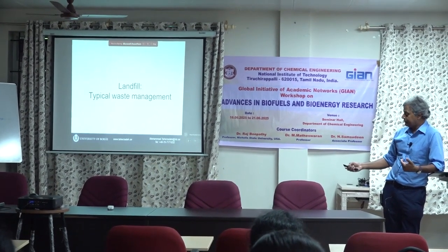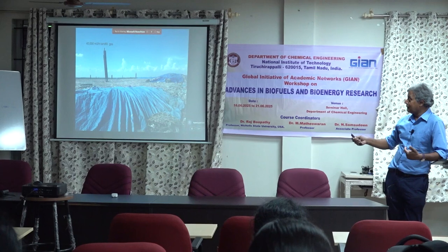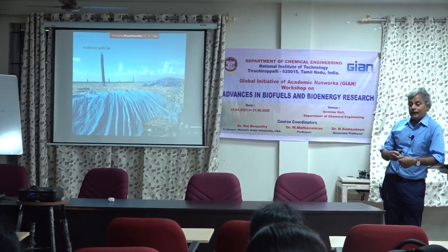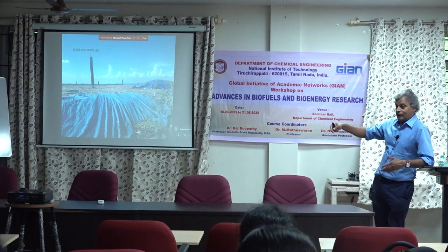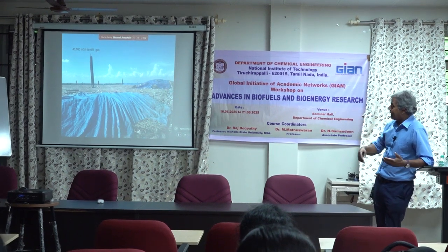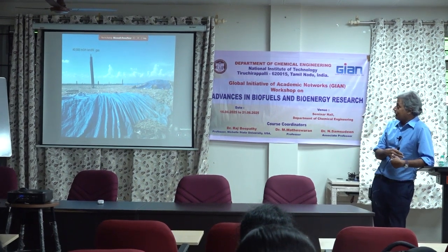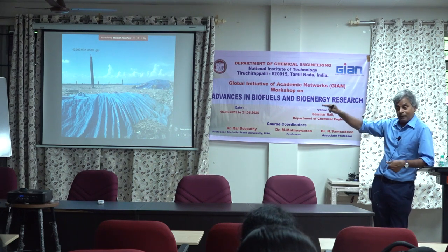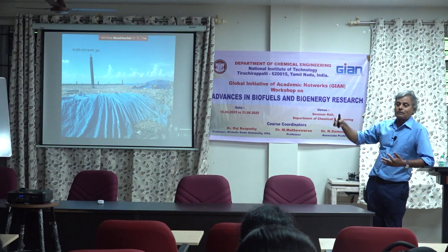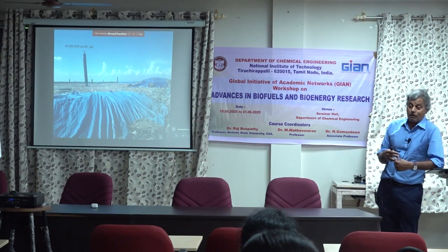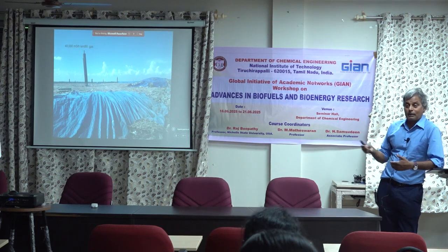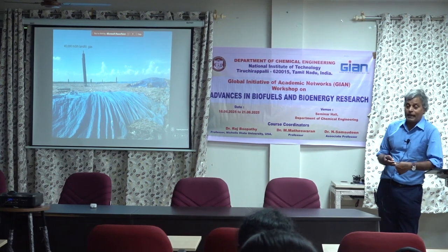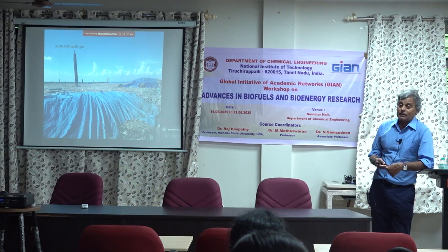That's how a methane recovery system looks like in a landfill. They have gas collection pipes all around, and in a decent sized landfill, you can collect 40,000 cubic meters of gas per hour, and then they have to purify the gas and make it 98-99% methane, and then it goes to a compressed gas system or natural gas pipeline. They sell it as a product.